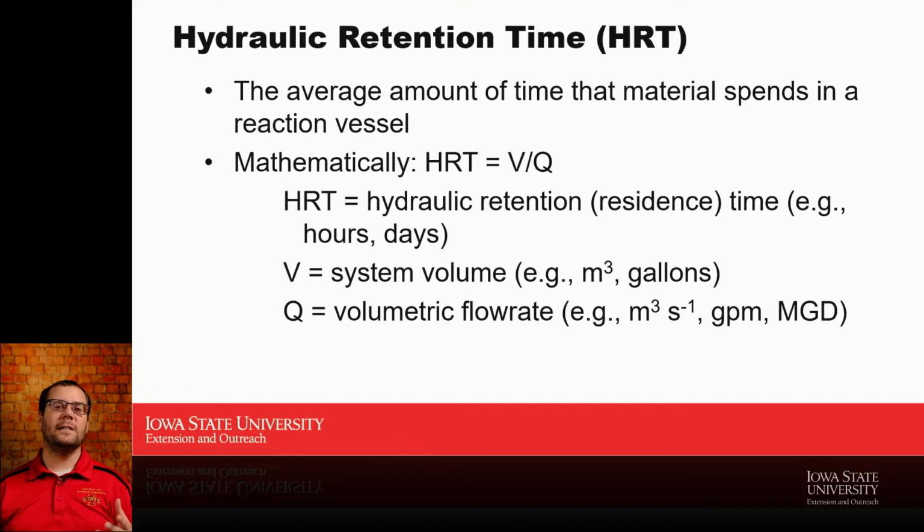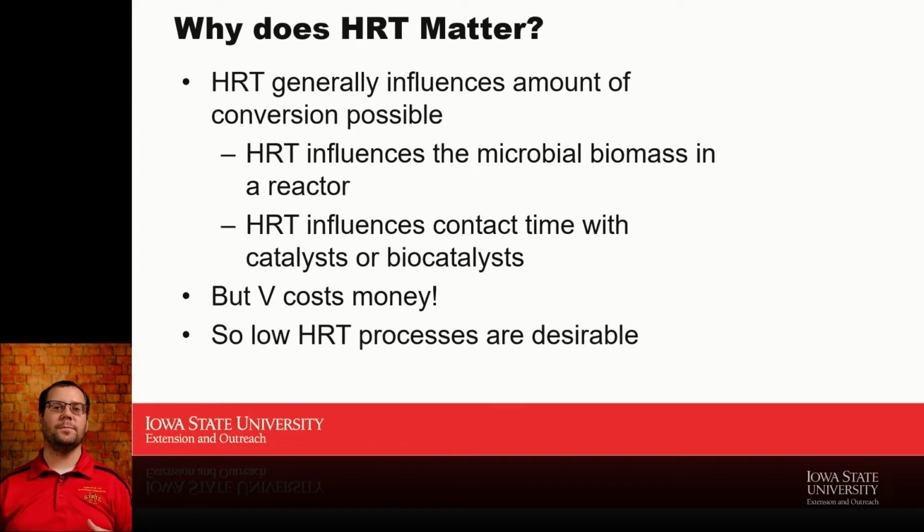So the hydraulic retention time, just to give you an idea of what it is, really is how big a tank do I have compared to how much I'm putting in and taking out every day. And that really is just how big do we need. And if I know how big a tank I need to build or buy, that really tells me the rest of my sizing and anaerobic digestion story, right? Because I'll know how big a tank I have. I can size my gas cleaning equipment from that chemical oxygen demand or biomethane potential that we already talked about. And that's really the basics of the two things to get you started on a process.